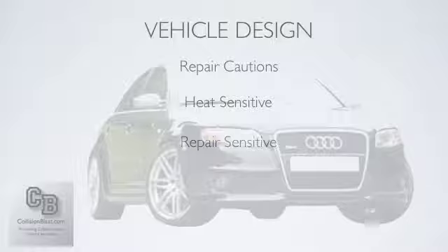So if it's involved in an accident, there are going to be unnecessary injuries. You can't really repair those types of steels because they're so hard. If you try to straighten it, it's probably going to crack. So most of your ultra high strength steels and boron are replace only. Like the intrusion beams in the car and anywhere that's indicated as ultra high strength steel or boron, there's not going to be much repairing. It's going to be replace.